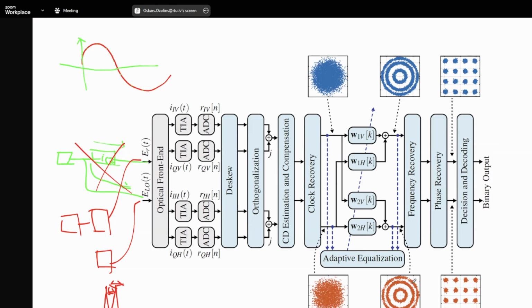If we talk about frequency noise, then it's number of rotations around the axis. So if you have a further distance, then the constellation rotates faster in one direction or another direction. And the phase noise is when the constellation rotates up, down, and at different angles. And that is what we call phase noise. So these two steps are critical, and most practical systems are heterodyne. So these steps are critical to make from amplitude like points in a standstill position.